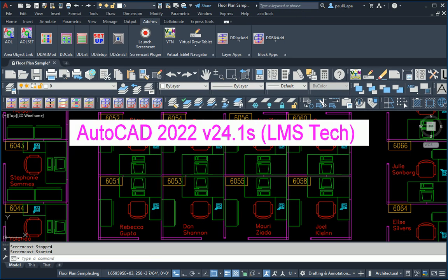The same can be done in AutoCAD 2022. Again, beginning with the circle command and selecting anywhere on the screen to begin my starting point for the radius, and once I click that, you can see as the dynamic input drags out, the dimensions change, and that dimension change also is reflected again on the coordinate display area down here, matching. So you have both matching locations, so if there is any discrepancy as to what really is or should be the dimension of the radius, you could compare. And 1'11", so I want 2 feet.